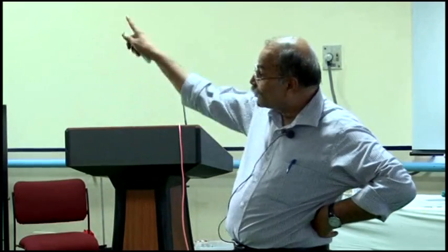So you take any axis, any line about that, the external torque should be 0, or any point, take any origin, and with that origin calculate what is the total external torque. Should be 0, there is no angular acceleration, it is in rotational equilibrium. Now tell me, just look at the door, what are the forces on this door as of now?